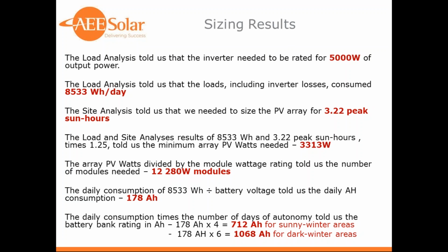So you want to make sure that you can not only accomplish what needs to be done in terms of your system sizing at the moment, but be able to do that also for future use. So if it's a 5,000 watt inverter, you actually might use a 6,800 watt inverter, or even an 8,000 watt inverter in this situation, to allow them to expand into the future and have a system that's going to work for them for the next 15 or 20 years.